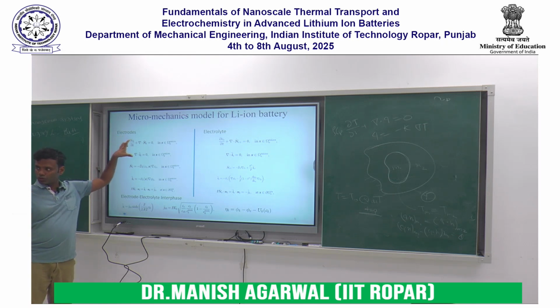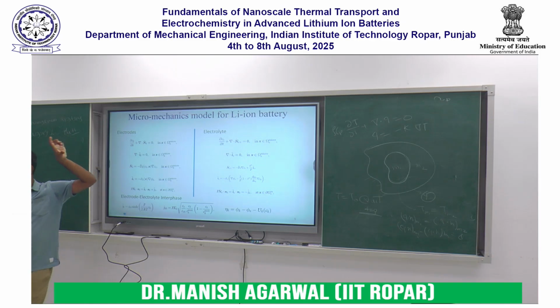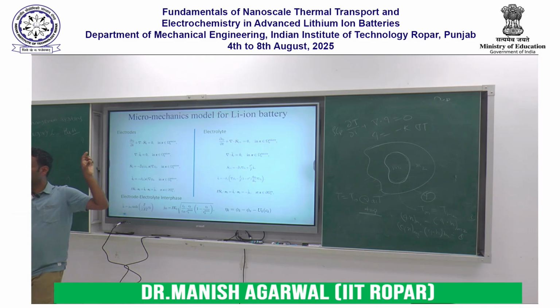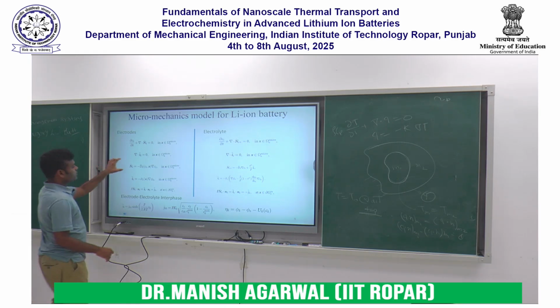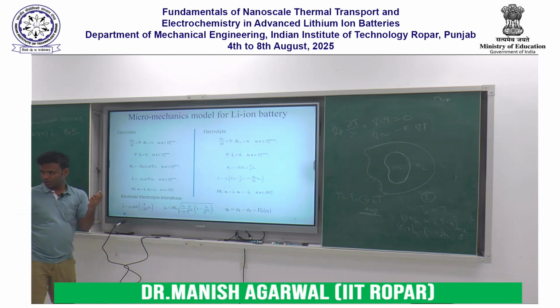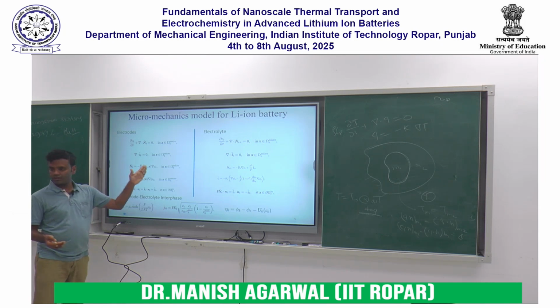One is the electrode domain, another is the electrolyte domain. In the electrode we saw that the first equation is the conservation of the lithium in the electrode particles. The second equation is a conservation of the charge again in the electrode particle, that is happening because of the flow of the electron. This one is the flux, that is given by the diffusion constant and concentration gradient. So this is how the flux and the concentration is related.